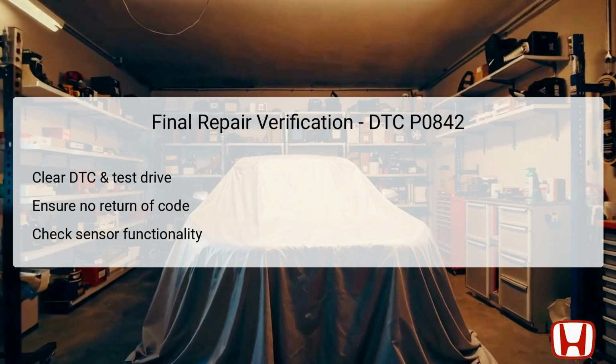It is essential to perform a final verification to confirm that the issue has been resolved effectively. Start this step by clearing the DTC from the onboard computer, which resets any stored trouble codes in the memory. Once cleared, take the vehicle for a test drive to observe its performance under normal driving conditions.